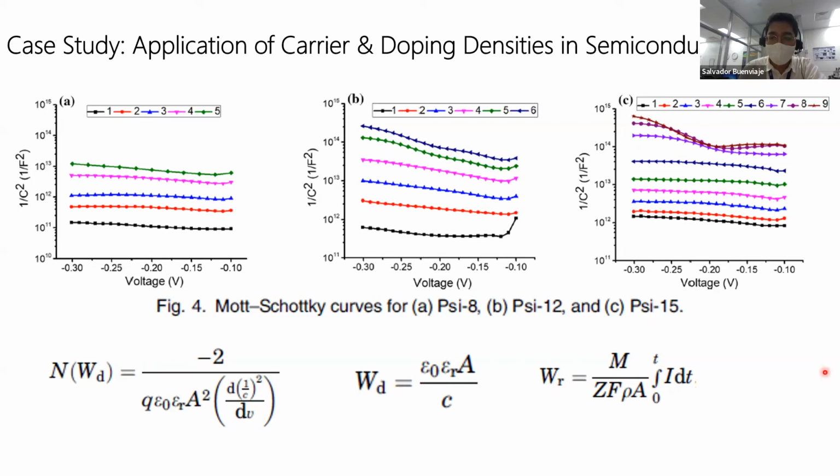The depth of the depletion region increased because the positive and negative ions become more separated as the reverse bias voltage was applied, leading to an increase in WD. On the other hand, by decreasing the capacitance, the electrical impedance also increased. These results show that as the slopes of the curve increase in each step of the Schottky test, the doping concentration decreased. So according to equation 1, this is the concentration. It is inversely proportional to 1/C squared.